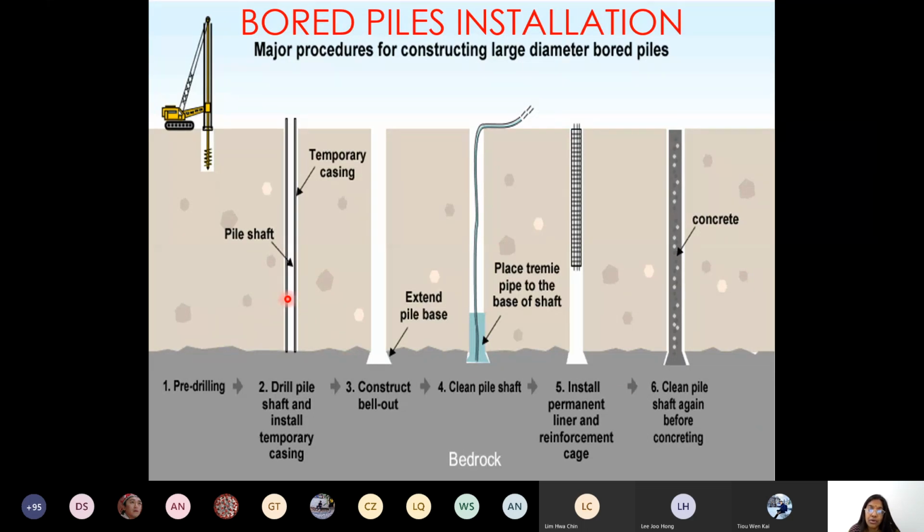Number one, above all you should have the borehole test report in your hand. If you want, I will show the pictures from my projects last time. You should know the different layers, at what depth soil, at what depth sand, at what depth rock, at what depth water. All this knowledge should be in your mind when you are working at the site. And then pre-drilling methods. What are the adjacent sides? What are the layers? All the knowledge about the surroundings should be there. And then drill the shaft.